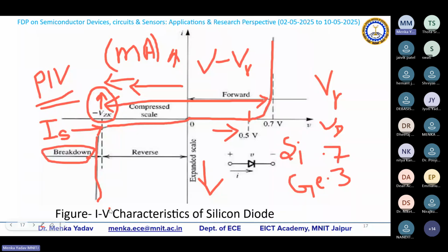Avalanche means sudden bombarding. For example, you might have heard the news, in Tehri, there was an avalanche of some hills or something like that. So that is sudden coming away from their original position. So that is destructive. We have to avoid that destruction. If we are not able to avoid that, the device cannot operate in the normal condition again. So that is known as the avalanche breakdown, that is seen in the normal PN junction diode.